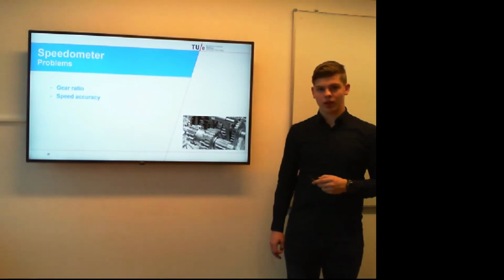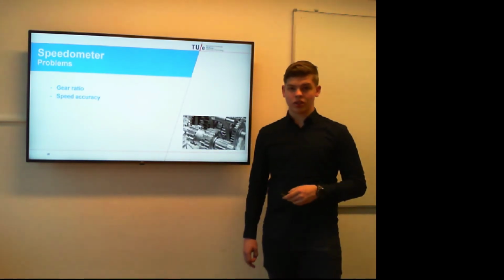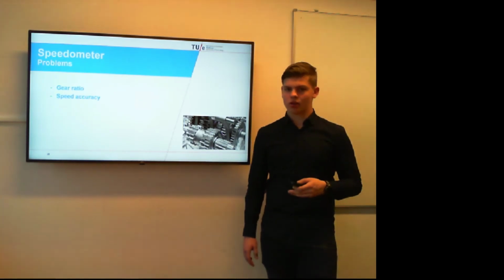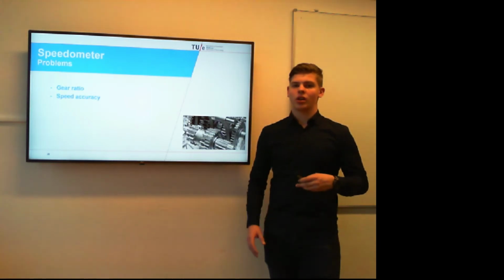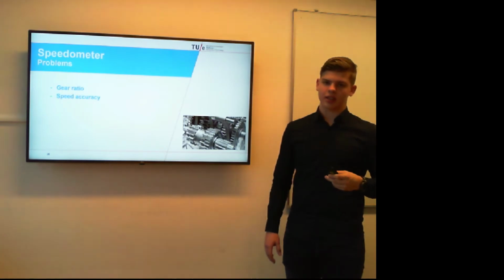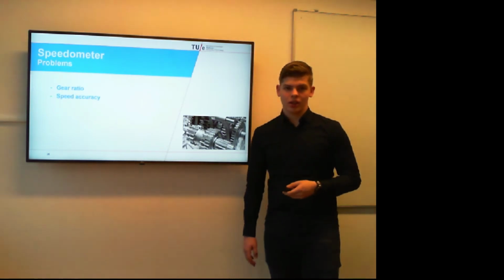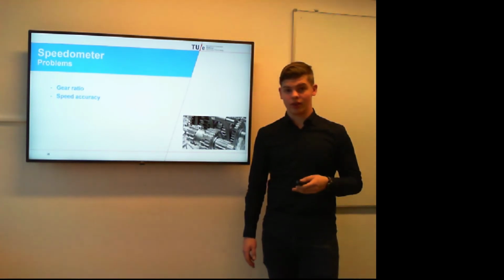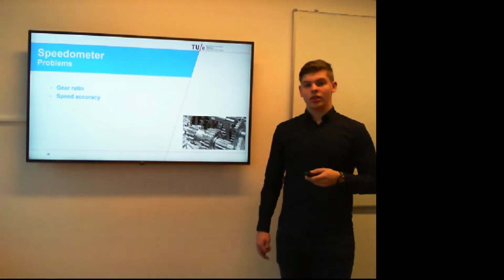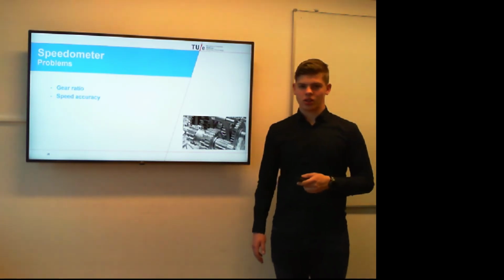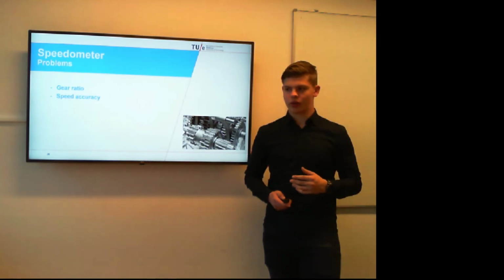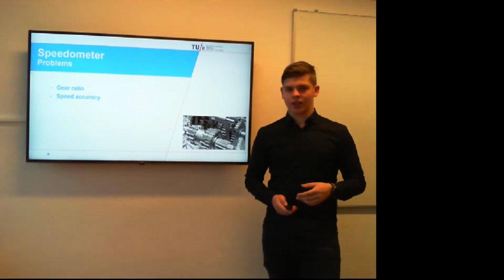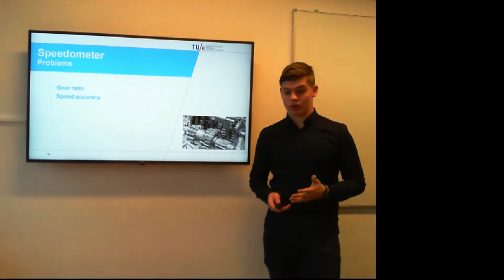Now, there were some problems we encountered during the progress. For example, there was the problem with the gear ratio. We were wondering if the gear of the actual sensor rotated at the same speed as the actual wheel. Turns out it wasn't the case, and we had to count every tooth on each wheel to calculate the gear ratio. We found out that it was a 1:3 gear ratio, so we added that into the calculations for the speed, and now we got the correct speed.